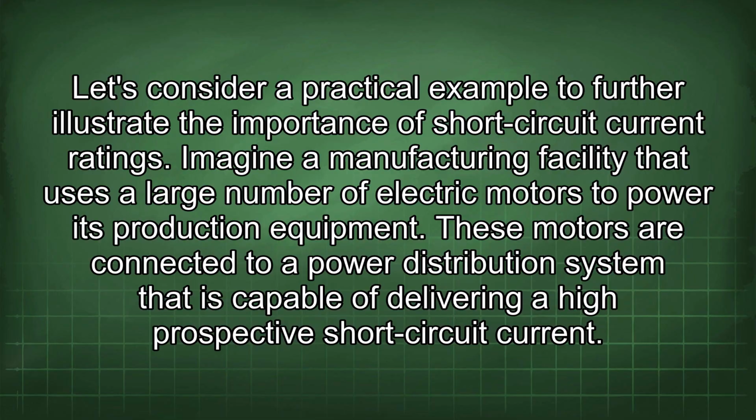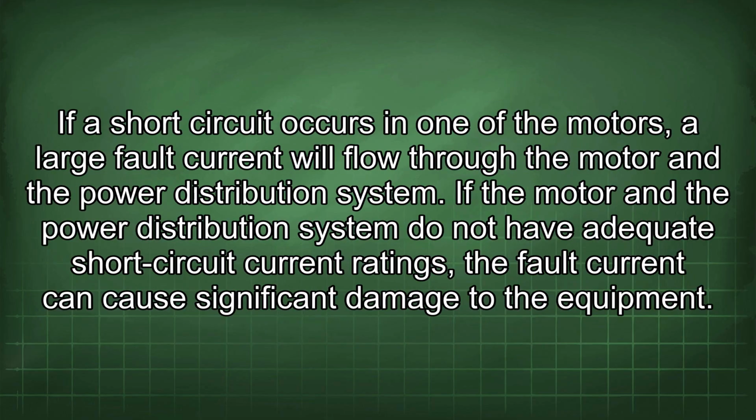Let's consider a practical example to further illustrate the importance of short-circuit current ratings. Imagine a manufacturing facility that uses a large number of electric motors to power its production equipment. These motors are connected to a power distribution system that is capable of delivering a high prospective short-circuit current. If a short circuit occurs in one of the motors, a large fault current will flow through the motor and the power distribution system. If the motor and the power distribution system do not have adequate short-circuit current ratings, the fault current can cause significant damage to the equipment.